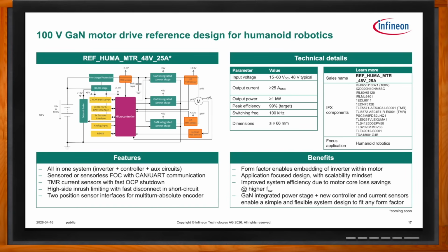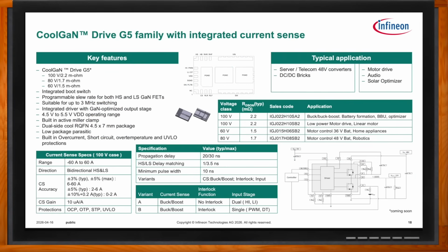And we have different types of sensors, including lossless current sensors that use tunneling magnetoresistive technology to get very high bandwidth, high accuracy, low drift, low cost. They're great. Those orange boxes on the right there on the motor phase. And we have position sensors as well that you'll see in a moment. So yeah, we have all of these parts. Let me next move to the power stage, what that looks like.